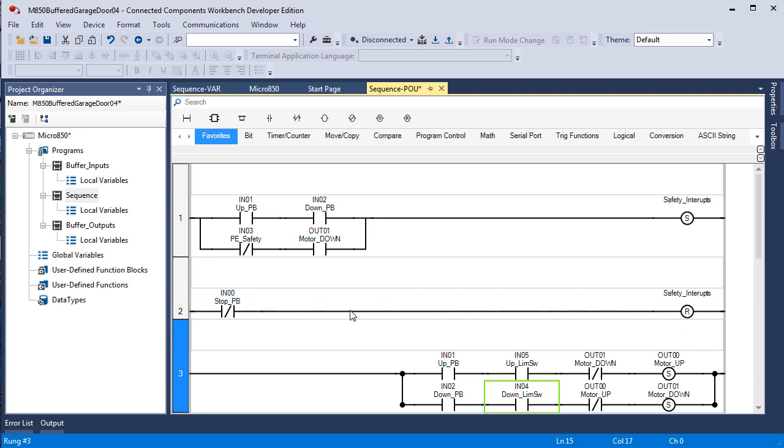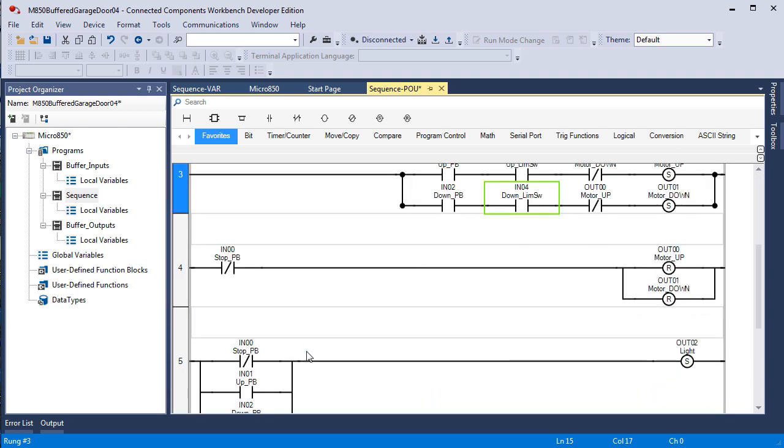So if you push the button, then this goes true because input 0 went off. That resets and eliminates this bit. Now if you're still holding down both push buttons, then this will set just as fast as you reset it.